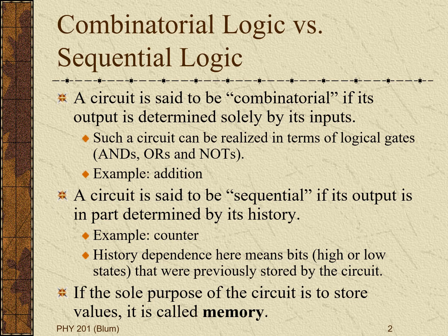And so we know we can write the outputs depending on those inputs as a truth table, and we can then build it based on a sum of products or product of sums approach. An example would be addition. The numbers that we wish to add are the inputs, and the output, the sum of those two numbers, depends only on those inputs at that given instant.